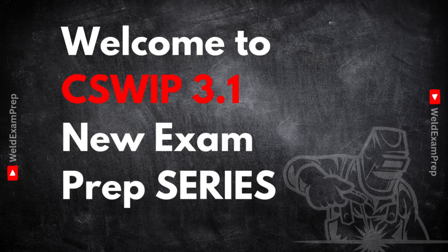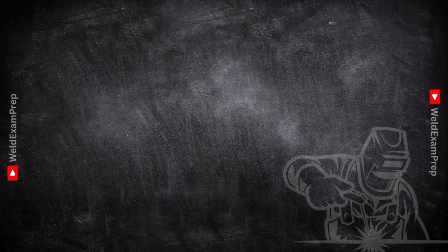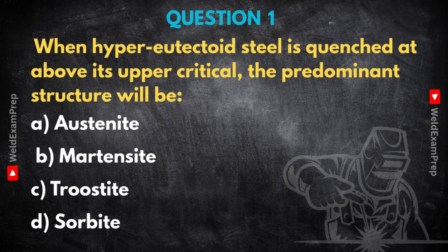Okay, sounds good. Let's start with a fundamental one about metallurgy. Question 1. It asks, when hypereutectoid steel is quenched from above its upper critical, the predominant structure will be A, austenite, B, martensite, C, troostite, D, sorbite.